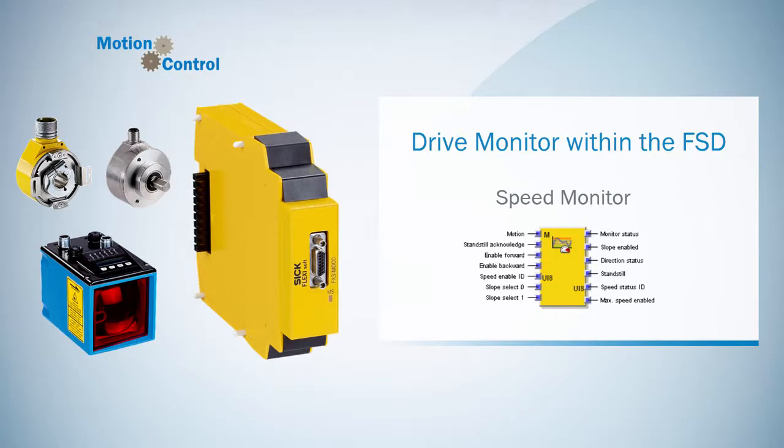The first input at the speed monitor is the input motion. Here the block gets all the information provided by the encoders. The other 6 inputs are optional. By using the input standstill acknowledge, the internal standstill detection is extended by analyzing an external signal. With the add of inputs enable forward and enable backward, the permitted movement direction can be activated.